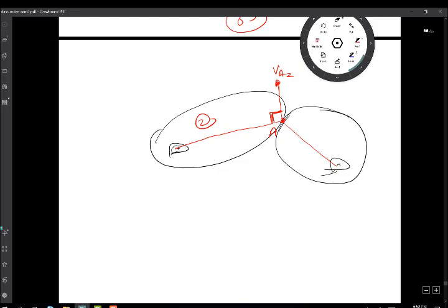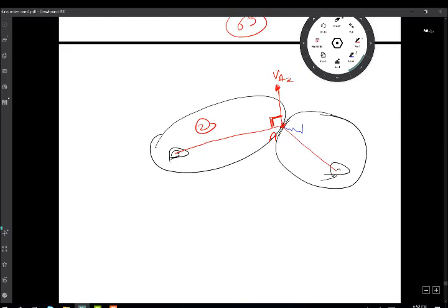Okay, go back to this. So this is the point which goes to that, okay? This is the line which goes to the pivot. So this line here is from the point of contact to this second pole. So this is point 1 2, this is point 1 3, this is link number 3, and the velocity, let's say, is something like that, VA being in 3. So the point of contact has two different velocities, right?